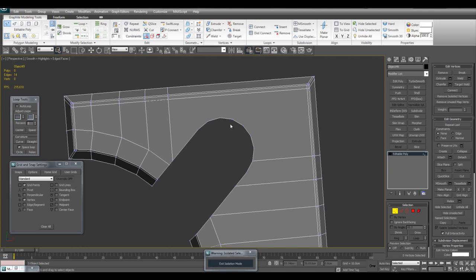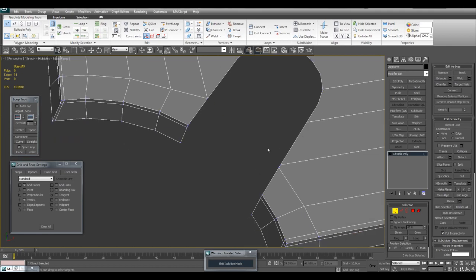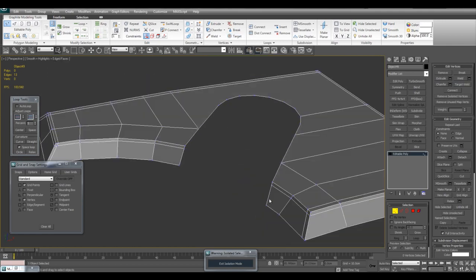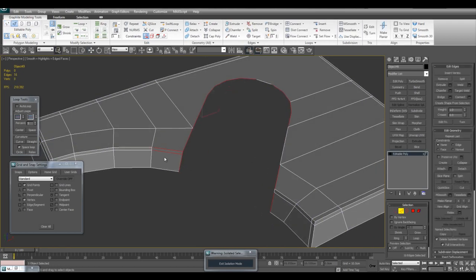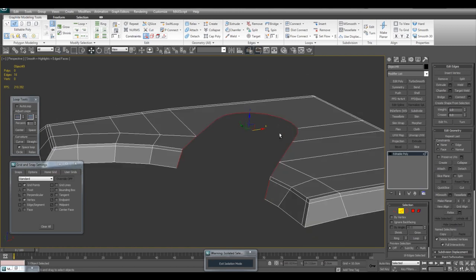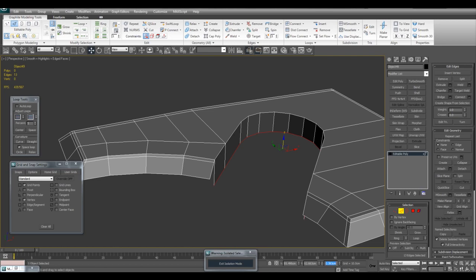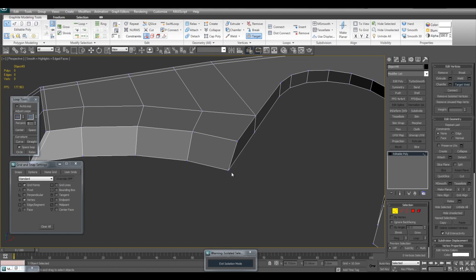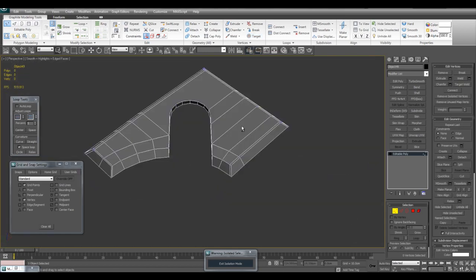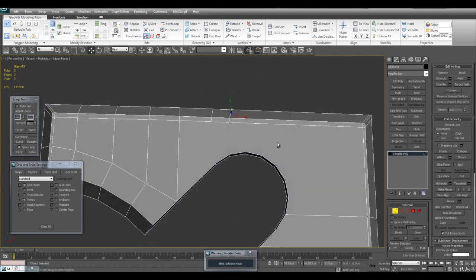And here I'll just leave this as the n-gon for now. I'll just do a little bit of basic welding. Select this and copy the Z value. Then select this. Select these edges. And hold shift and extrude this down. And paste that Z value right here. Remove this support loop for now. And weld it right here. So there we go. And now I can simplify or turn this into all quads.